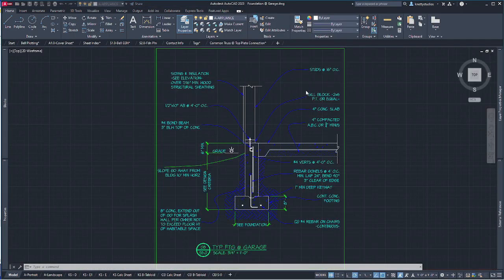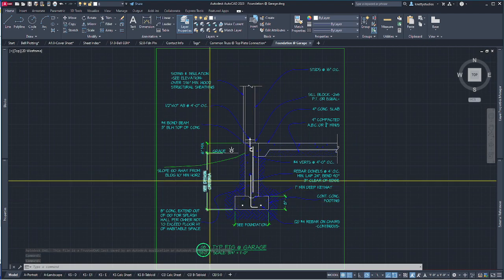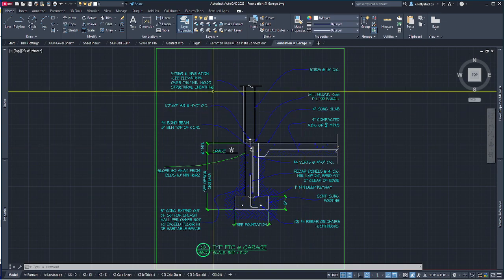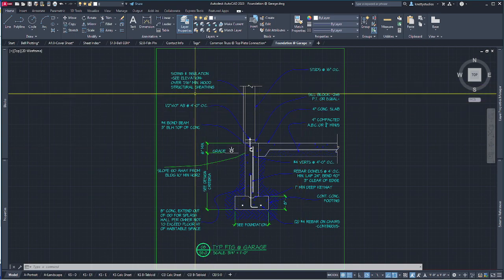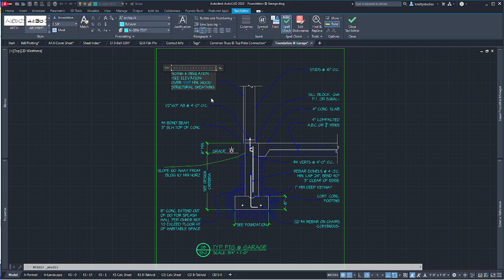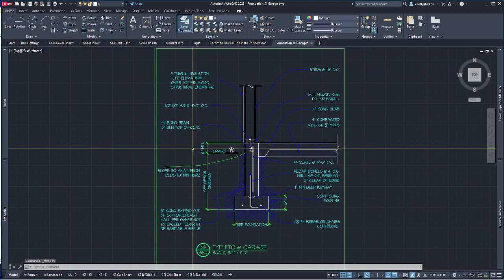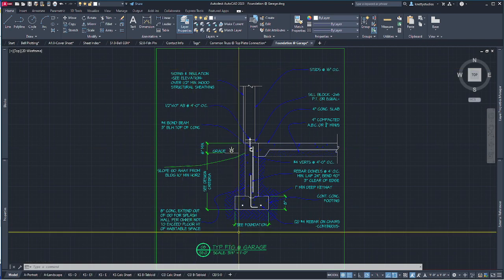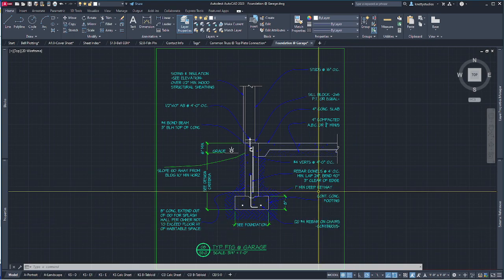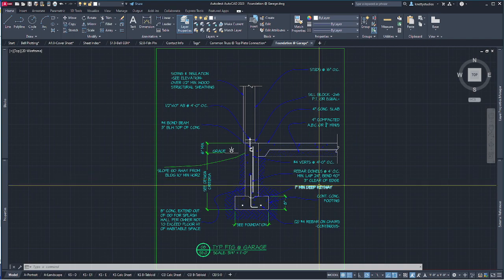Let's look at this foundation at garage one. It's pretty straightforward too. See design criteria for the depth. All of our wood products need to be 6 inches out of grade. That's a code standard. Over 7/16 minimum wood structural sheeting. Now, this is a client who requested that I upgrade this to a 1/2 inch. And so that is special. That's why I make a copy. And then I'll go in and make any changes to this to be particular to the project itself.